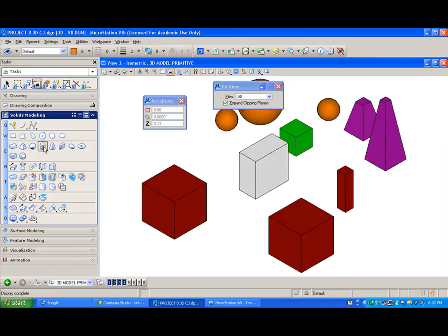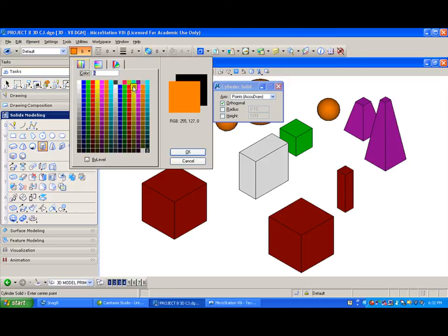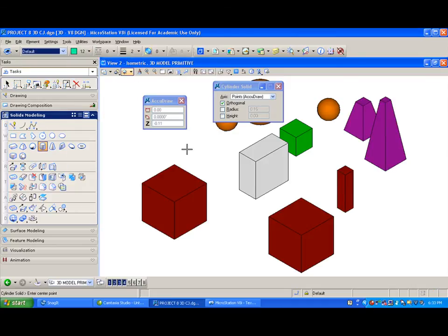The next tool we have is a cylinder. I want you to click on that cylinder. The cylinder is just like drawing a circle, top view, we'll say 0.5 per radius. And we just pull it up and say, what's the height of this cylinder? Let's say it's 0.5 also. That's how easy it is to draw a cylinder.